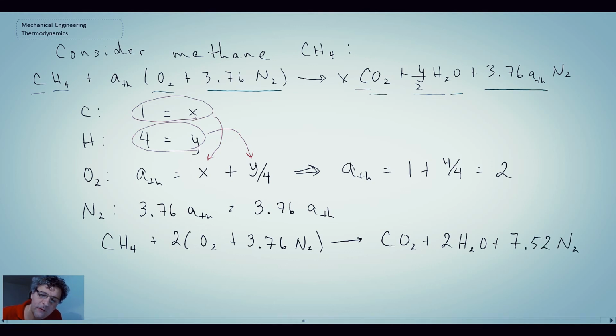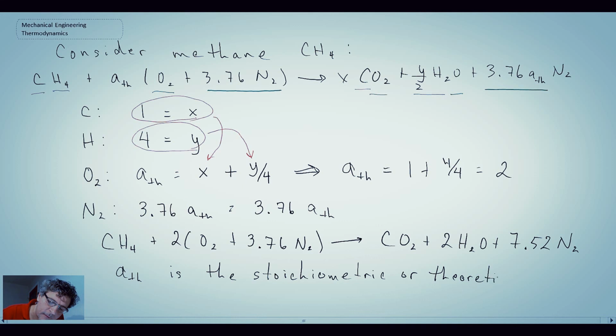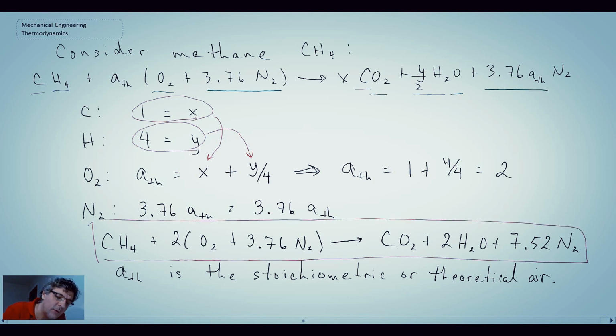So that would be our reaction equation, and A theoretical is the stoichiometric or theoretical air. So that would be our combustion or reaction equation if we had a stoichiometric balance between the air and the fuel coming in.